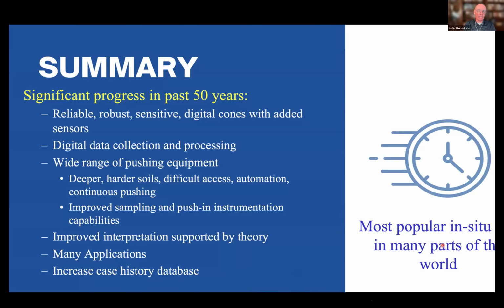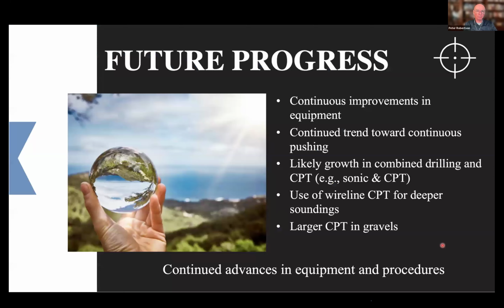Now, obviously, if you've got an area that's bedrock, hard rock, you're not going to push the cone. You can push the cone into soft rock, like these residual soils, or here in Southern California, we have relatively soft sandstones and siltstones, and we can push the CPT into it. So you can push it into pretty hard ground. If you've got really dense gravels, it doesn't work there.